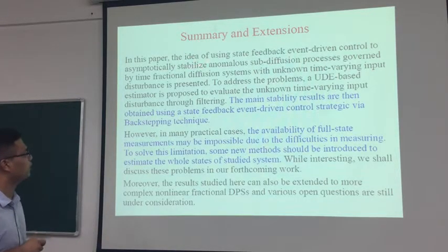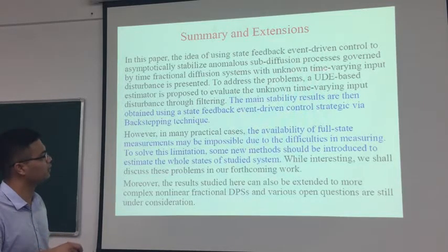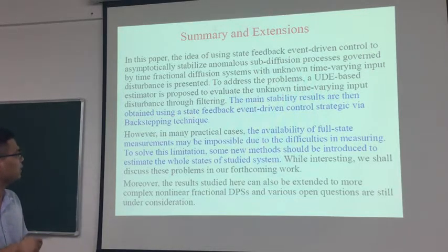Okay, finally, we give our summary and expectations. In this paper, the idea of using state feedback event-driven control to asymptotically stabilize anomalous subdiffusion processes governed by a time fractional diffusion system with unknown time-varying input disturbance is presented. To address this problem, a UDE-based estimator is proposed to estimate the disturbance. The main stability results are obtained by using the backstepping technique, based on state feedback event-driven controls.